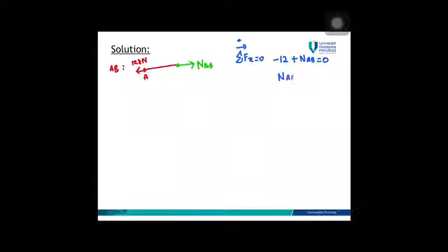When you draw the free body diagram for BC, you need to start from A. You cannot take only the BC cross section because the structure needs to be in equilibrium. If you just take the free body diagram for BC only, then your structure or your elements are not in equilibrium.